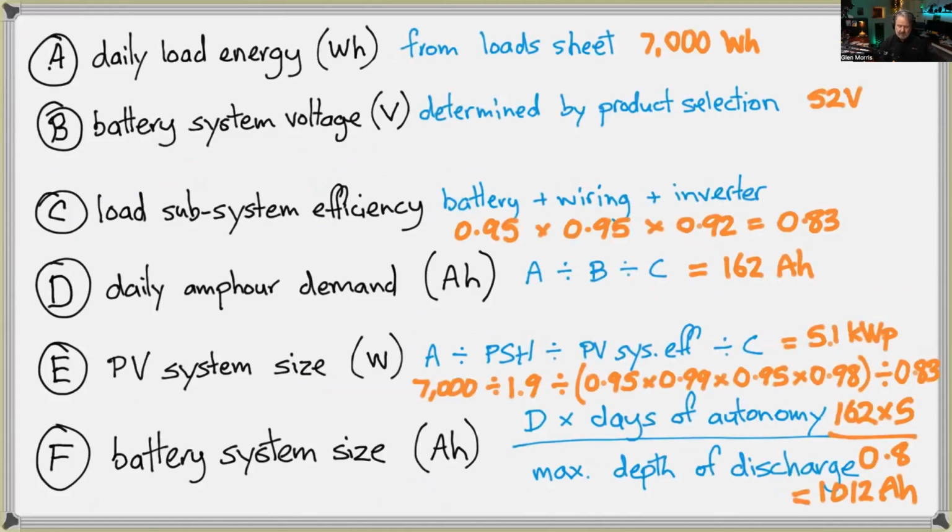Here we go. So that number there reflects the loss due to temperature. Now, you see it's only 5% loss, not 10, as I just did as an example. The reason for that is, in this system, I've chosen the design month to be midwinter, and midwinter in Melbourne, and it's partly shaded too, the site. So midwinter in Melbourne, the ambient temperature isn't 25 degrees, unfortunately. It's, well, at the moment here it's about 10 degrees.